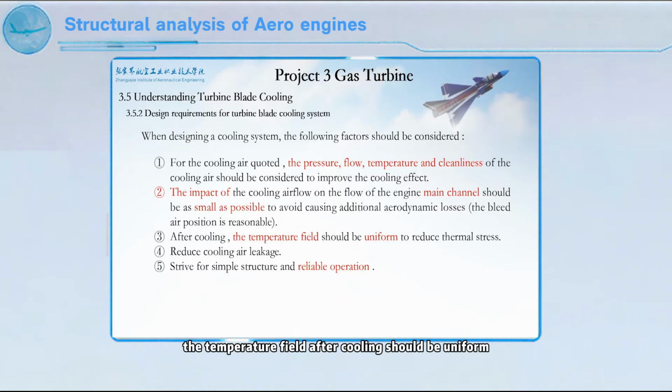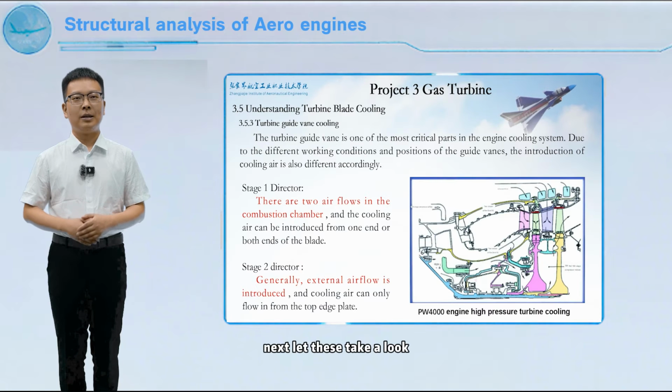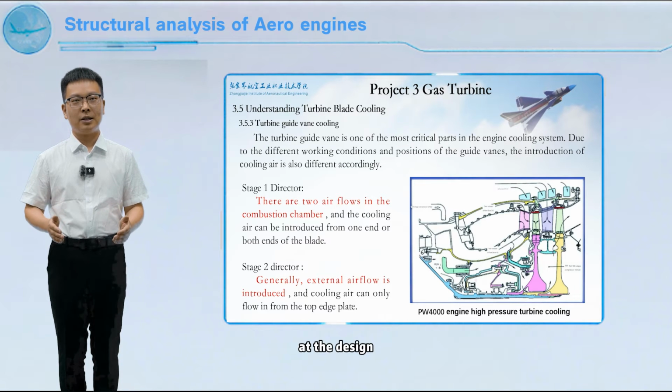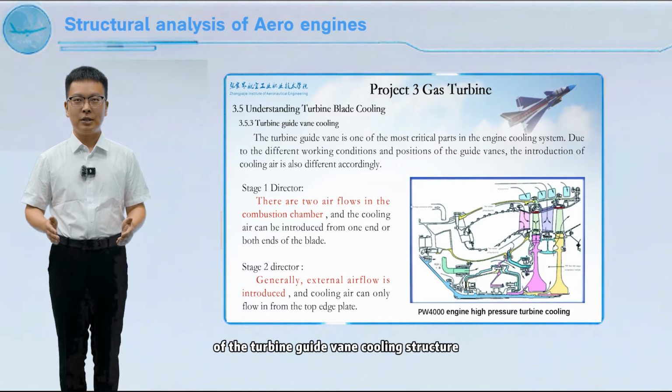Third, the temperature field after cooling should be uniform to reduce thermal stress. Fourth, reduce the leakage of cooling air. Fifth, strive for simple structure and reliable operation. Next, let's take a look at the design of the turbine guide vane cooling structure.